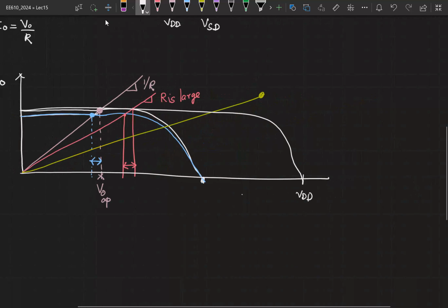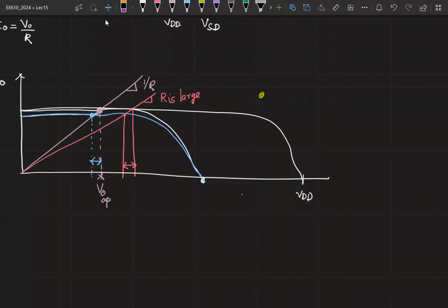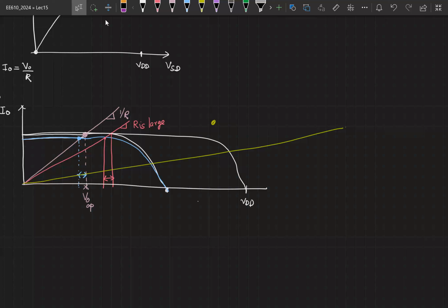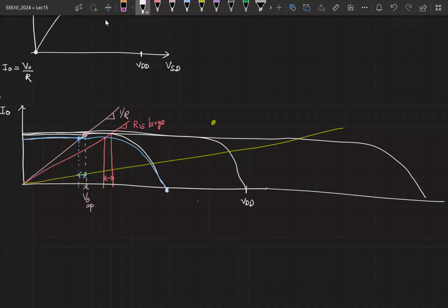But then your manager tells you, you need to get even more gain. So you decide to make your R even larger. So now your R, instead of looking like this, looks like this. Let's make it even larger. We are very ambitious people. So we made our R even larger, the slope reduced further. Now what do we do? Increase the VDD further. So we went on increasing the VDD. And eventually at some point, you will have to plug your transistor directly to the 220 volt socket.